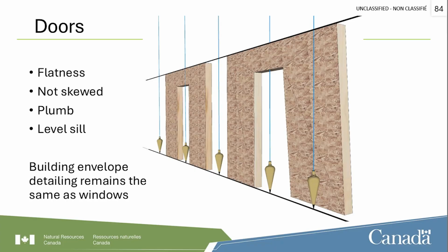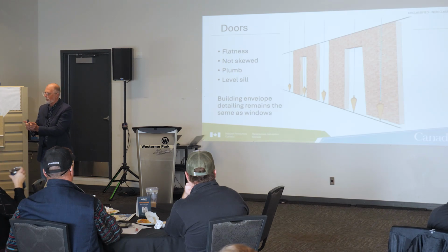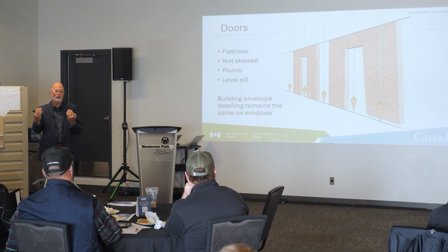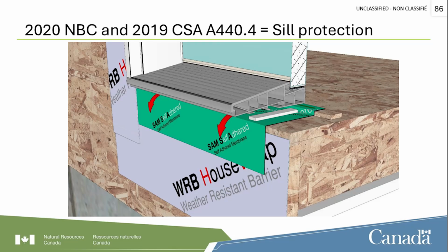Doors, by far, the most important thing is when you cut that bottom plate out, that better be straight and flush. Because how often does the framer cut the bottom plate out and then that little short stub wall that's butted in on this side is not secured? And then he goes, oh, it's not secured. So he just nails it in without checking, and now you've got a wall that's askew. And that creates all sorts of grief when it comes to installing doors.